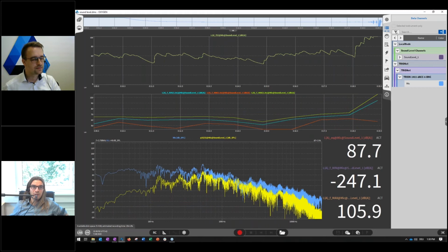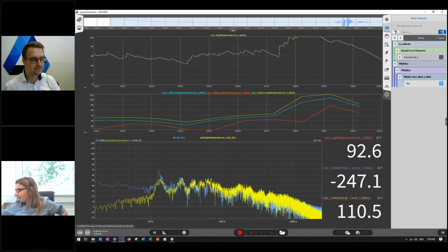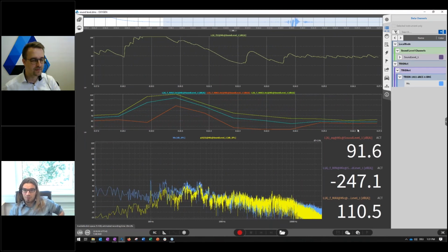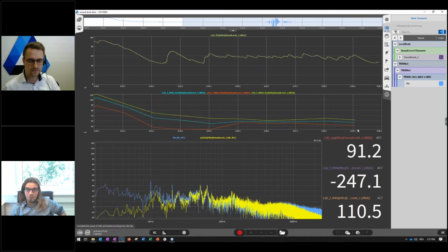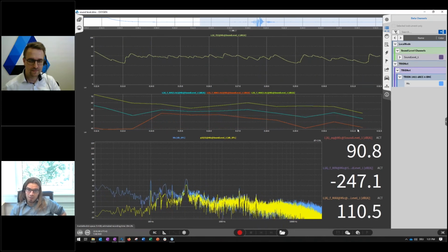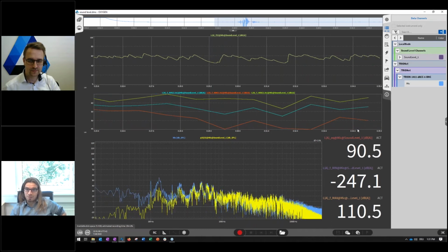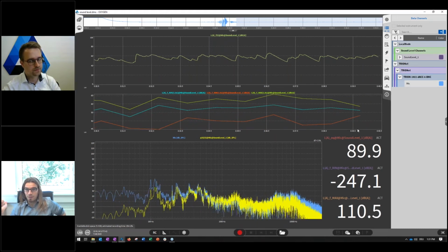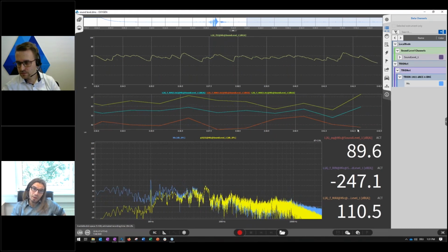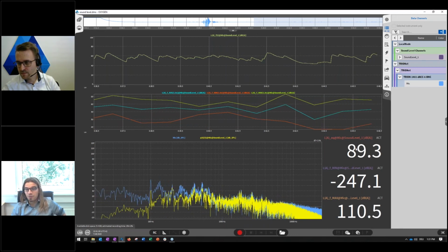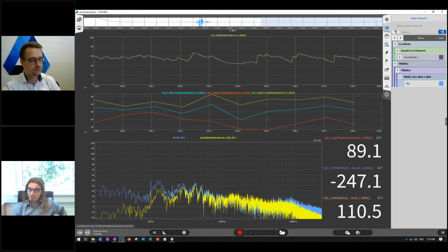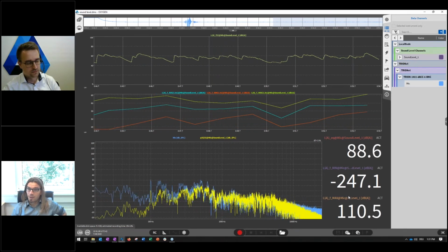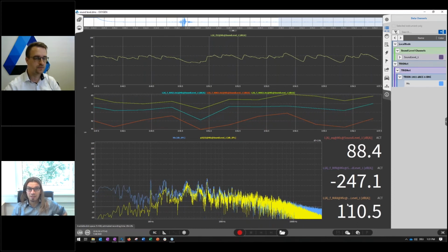And on the upper recorder, you see the time-dependent trend of your sound pressure level, which is frequency-weighted on the one hand. So you can weight the signal with ABCD frequency weighting, and you can also apply a time weighting, fast, slow, or impulse on this channel, which are defined in the relevant sound pressure level standards. On the other hand, the LAEQ, the energy equivalent sound pressure level, is calculated. The minimum and maximum occurring sound pressure level during the measurement will be determined and automatically calculated.